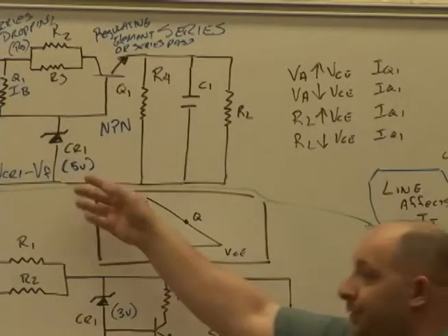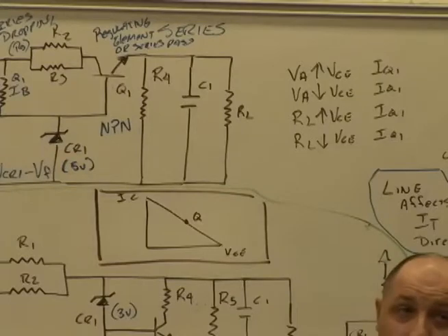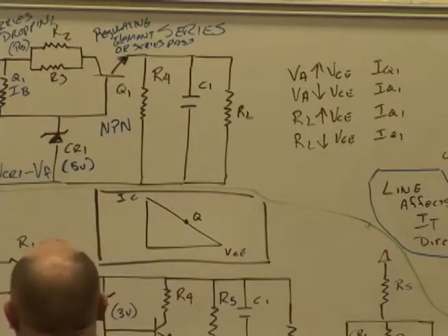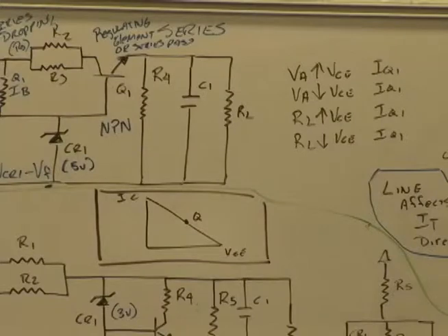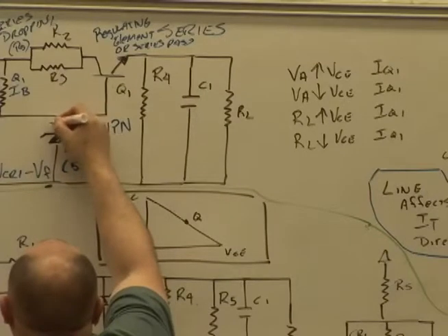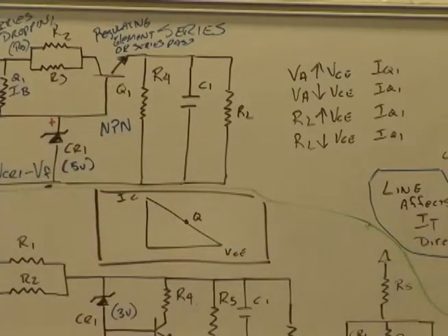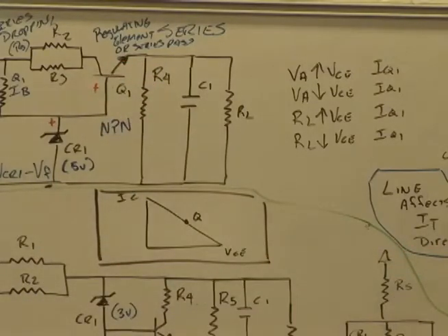But first, why do we subtract the forward voltage? It's a polarity thing, remember? Because the zener's in the circuit backwards. Negative is down here at the bottom, isn't it? Look at the source. P-type material is attached to the negative portion of my circuit. Something's already wrong. It's backwards. This is the more positive part of the circuit. It's the cathode, so you should be able to tell it is in the circuit backwards. It's a polarity. Whenever you take a voltage drop across a component, it's going to have polarity. That is what I like to call BO1 stuff. Isn't that an NPN transistor? Yes. Oh, series opposing, got it. Subtract the forward voltage.